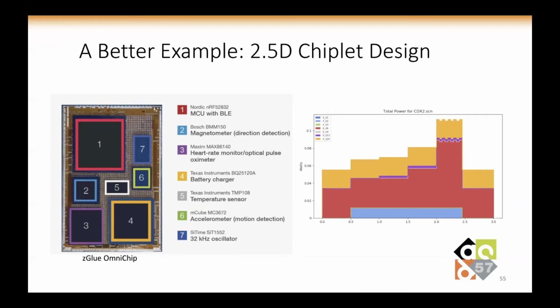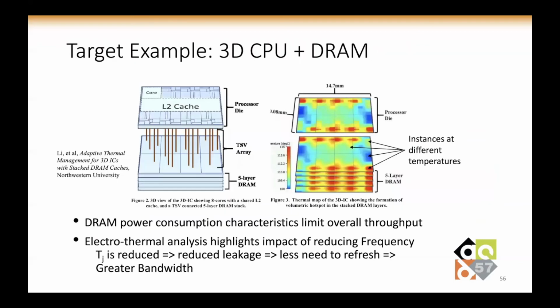And the fact that power data can be modeled with any of the multiple representations provides great flexibility in model creation. Some of these models use multiple states, some use a single state, some use expressions, some use scalars, but all 7 chiplets are modeled using UPM. Now, this next example speaks to where both system design and modeling technology are headed. Getting good system-level power estimates is necessary, but in the end, it is not sufficient because good thermal estimates, thermal analyses are also necessary. And this is another area in which UPM provides great value.